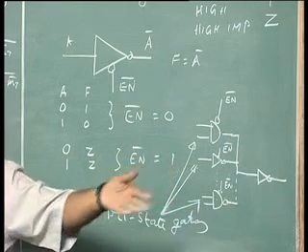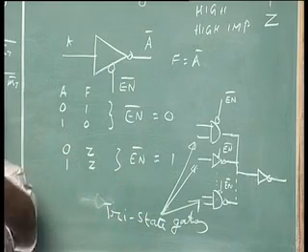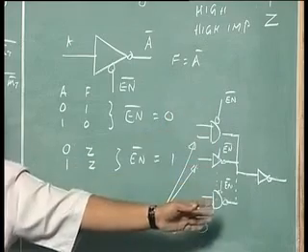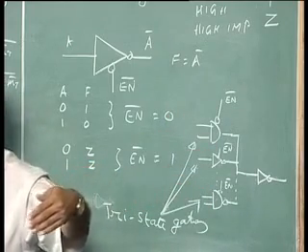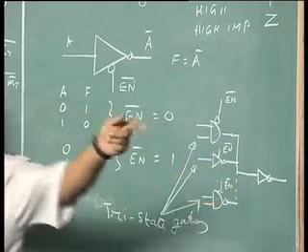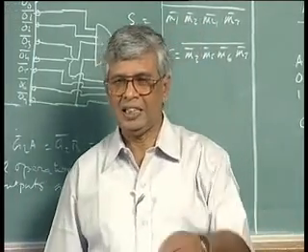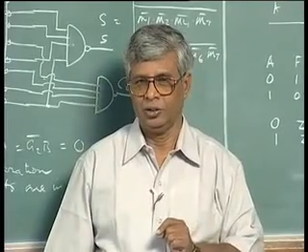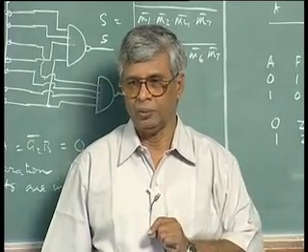It transports a lot of things at the same time, right? Many people can join the bus and then go. Many signals can join and go. So the common bus is there. All these outputs feed into a common bus. But of the common signals, only one is useful to the input. So I have to disconnect the other inputs from the bus. Physically disconnecting is not possible, so I electrically disconnect the other inputs which are not required at a given time.